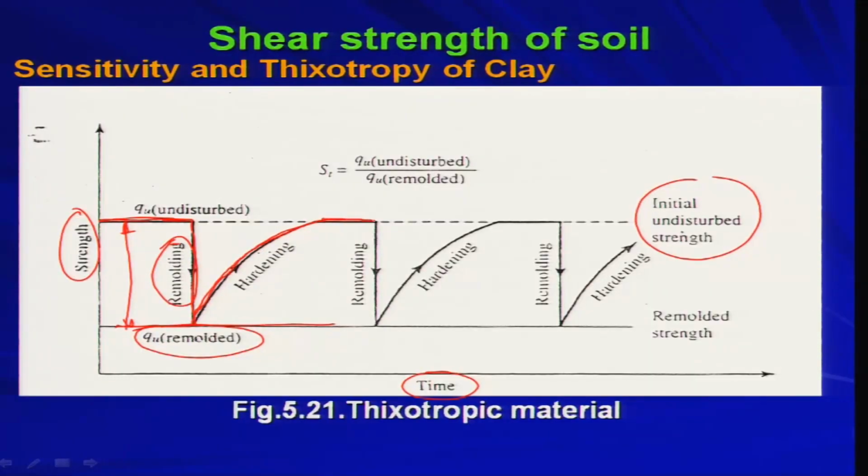After that, if you again remold the soil sample, it will come down to this. Again with time it will regain its strength, and it will become the same soil you had in the field. This is a very interesting phenomenon. Very few materials in the world show this kind of characteristic.